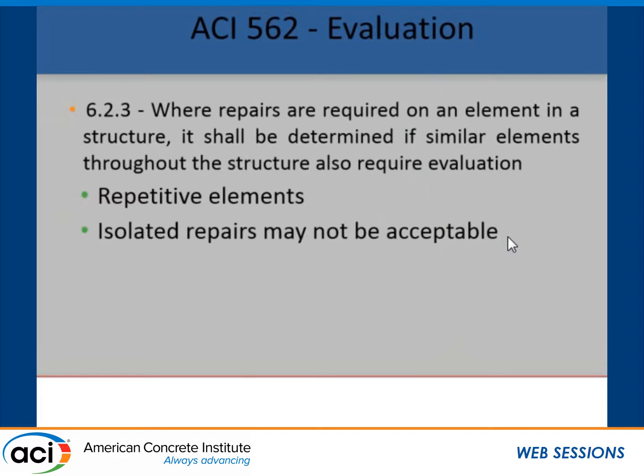Repetitive elements. If I notice that there's one, let's say a punching shear cracking around one column, and I know that I got a couple hundred of those, if I just have cracking at one, in terms of a standard of care, this is suggesting that it's not enough to just look at that one location. You have to think about repetitive elements. If you're designing repairs, maybe just doing one repair is not enough. And that's something that's important to communicate to your clients. The gentleman earlier says you need to communicate with your owner. That's important because it's not enough.